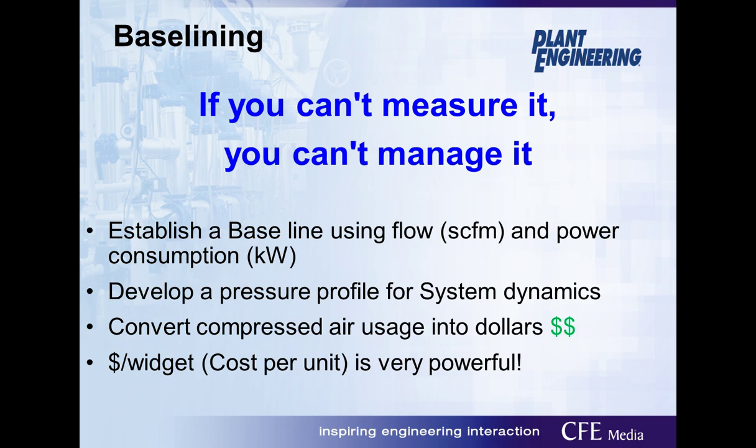Really, the key was we talked about baselining. If you can't measure it, you can't manage it. That's said many times. So you really want to establish a baseline using your flow and your kW. You want to understand a system profile so you know the dynamics of it. And you want to convert that compressed air usage to dollars, and put it in a cost per widget.